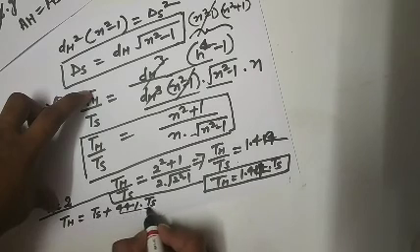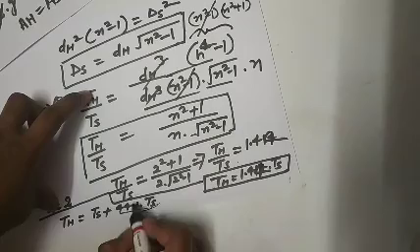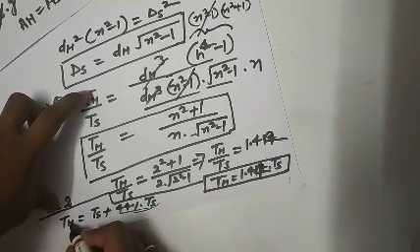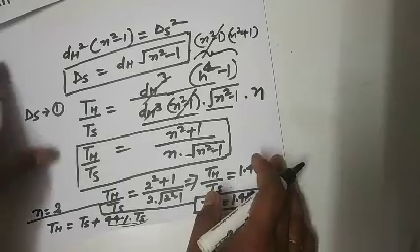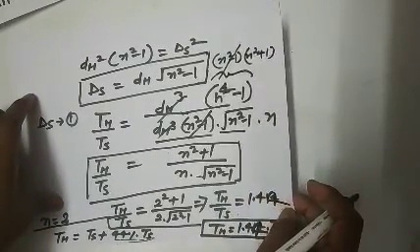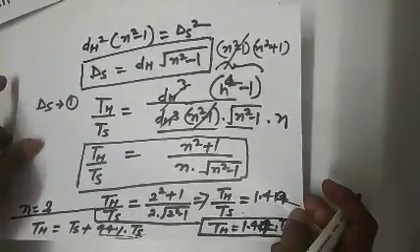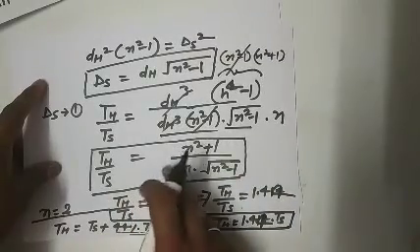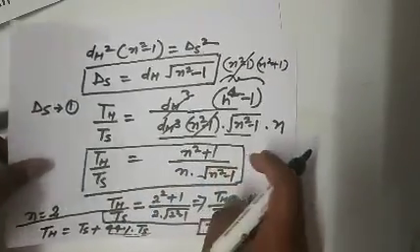So this one is the amount by which the hollow section is higher. So for the given condition, we will choose the hollow section in place of the solid section, right? Hollow section in place of solid section. That is the final conclusion from this strength comparison equations.